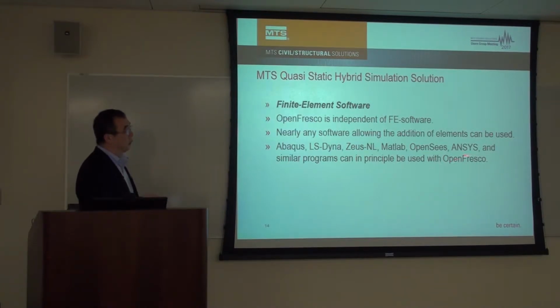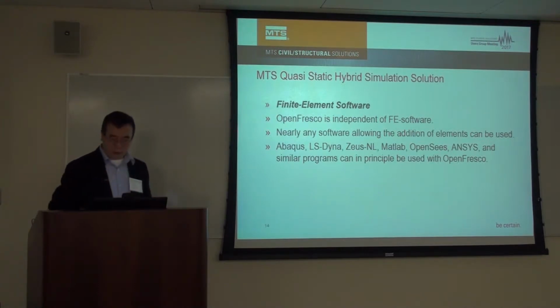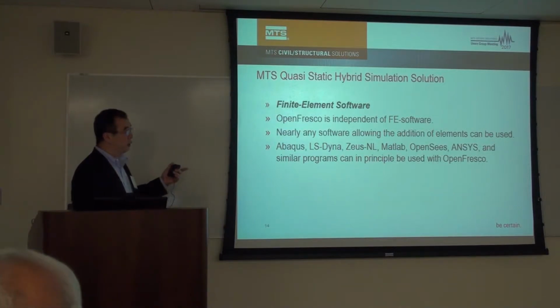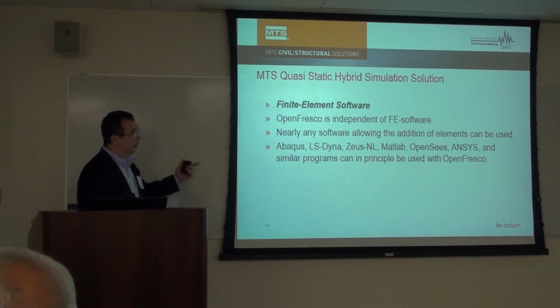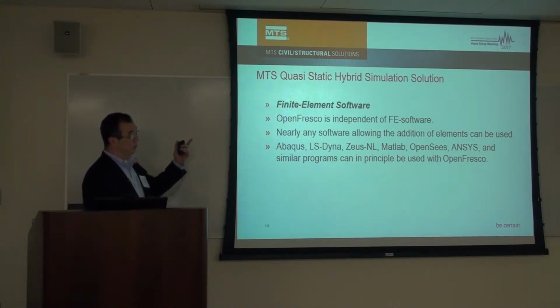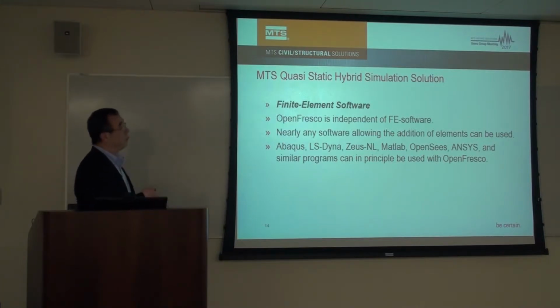So we developed the connection between OpenFresco and ADAMS. Later on, I will talk about that. So this solution is very flexible. You can use any FEA software as long as it has a user-defined element function. If you can define an element in that package, then you can connect that package with OpenFresco and our controller, and do hybrid simulation.